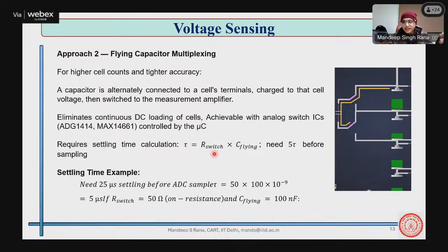First, these things, and second thing which we need to take care of, which I have not written over here, is that generally these wires and the leads which we are connecting there have some inductance involved, which causes our circuit to actually become an RLC circuit, which has a damping nature like this.